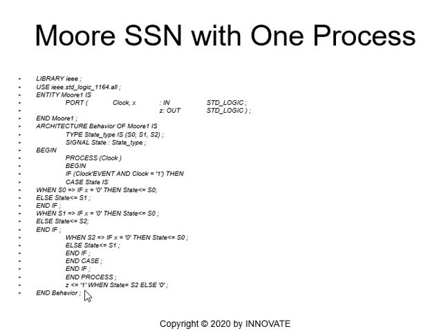Now Z will be assigned 1 when state is equal to S2, else it will be assigned 0 in the behavior. So we define the state, since the output is 1 only in one state, which is S2, else Z will be 0. By doing this, we finish the code for the Moore network.